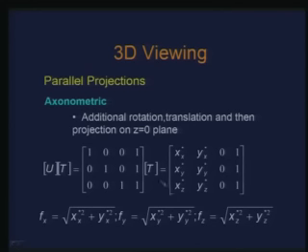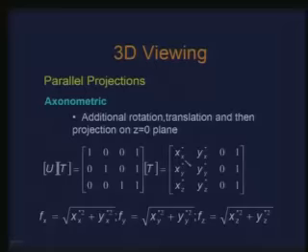What do I mean by foreshortening? Basically, the distortion which has happened in each dimension or direction. If I have the unit vector 1 0 0 transformed to, let us say, x_x, y_x, where the suffix x refers to the unit vector in the x direction, then the foreshortening, or the scaling or distortion, is given just by this, which I call f_x, the foreshortening in x.